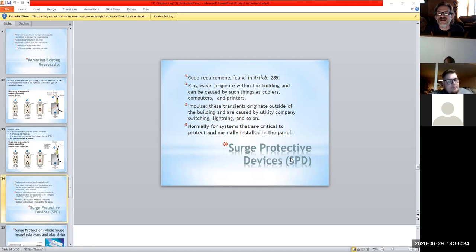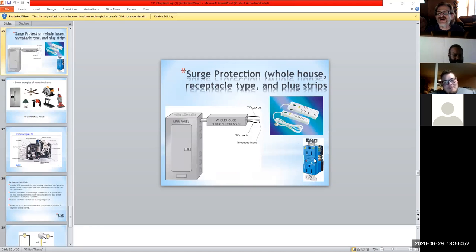But anyway, the book also, this chapter goes through and talks a little bit about surge protection. Now, believe it or not, you can buy receptacles that have built-in surge protectors with them. They look kind of weird. They're these blue guys like this, and they'll look like an AFCI and look like a GFCI, but they're really not. They got a little turnable thing to them to tune them, if you will, to set them to the rating that you want them to be.